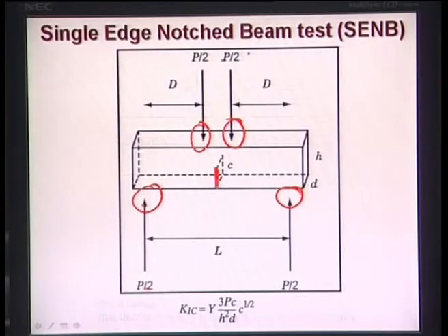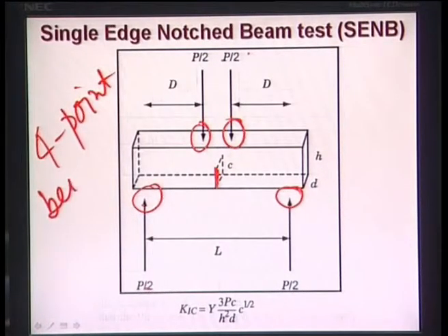Okay, coming back to the discussion on this long crack fracture toughness. Essentially the single edge notch beam test specimen contains a notch as well as an associated crack of length C. Remember that when you put this in the 4-point bending configuration, the loading side will always be under compression.